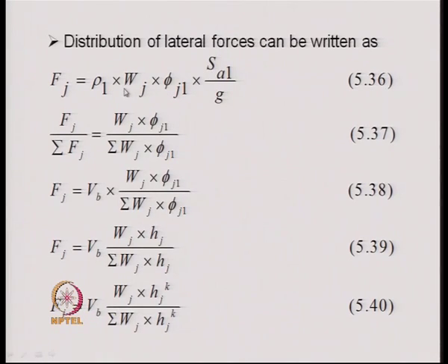So, this is a typical lateral force that we obtain in each mode of vibration in the response spectrum method of analysis. Now, if we concentrate only on the first mode of vibration, then the spectral acceleration, the mode shape and the mode participation factor all correspond to the first mode only. With the help of this formula one can find the force at different floor levels j.